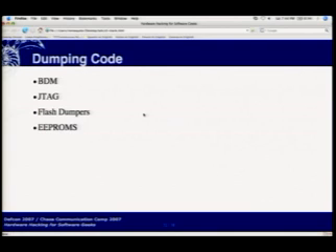However, the headers are highly variable. I've got 2 devices here, both of which have JTAG headers. One of them has 10 pins, one of them has 14. The connections are different, and it's been largely trial and error trying to get JTAG connections into these devices. It supports a lot of the same stuff as BDM.